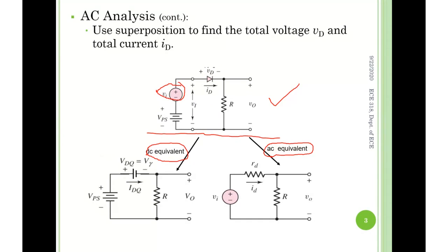Short, right? Be careful, independent source, okay? Both here and here are independent, so we can eliminate them. If dependent source, we cannot touch. Remember, we cannot touch, okay? Has to be independent. And if they are, then just short the voltage source and open the current source.